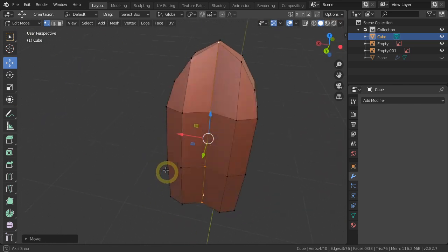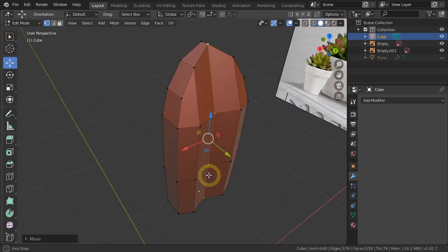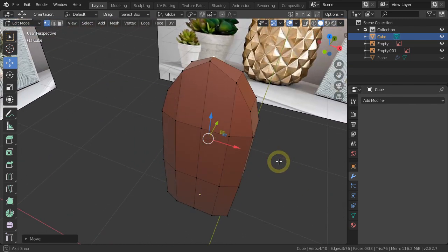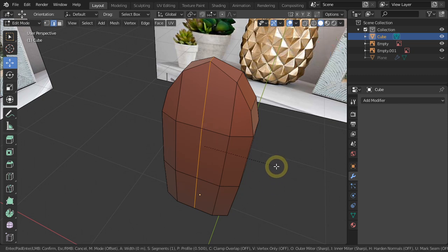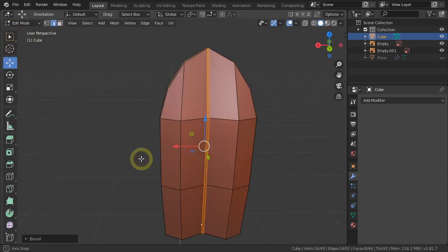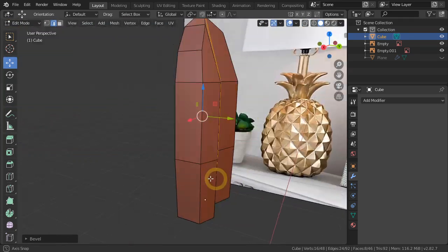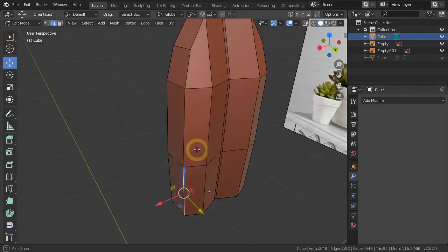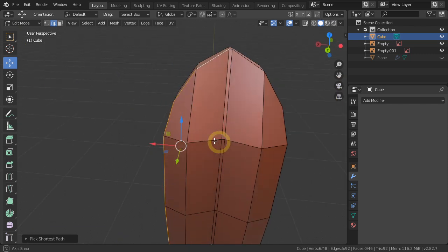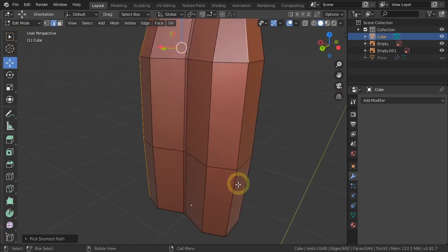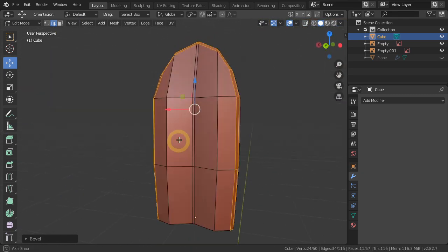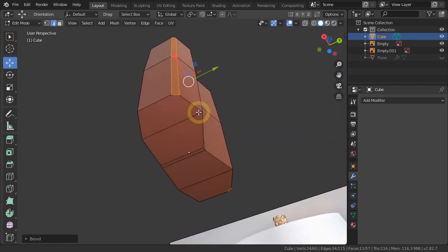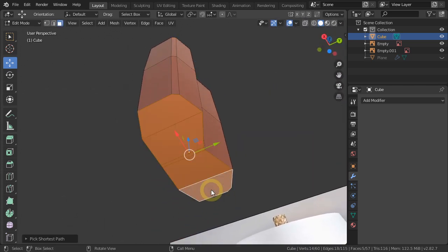To make the center lines look sharper when later subdivided, we can double the edges using the bevel command. So hold Ctrl and click this vertex. Go to the edge mode and then press Ctrl B. Create a small offset so the result will be sharper when subdivided. Next, we want to make this edge loop a bit sharp also when subdivided. Ctrl B again and make the offset to about this wide. We don't need the faces at the bottom part, so let's remove them.